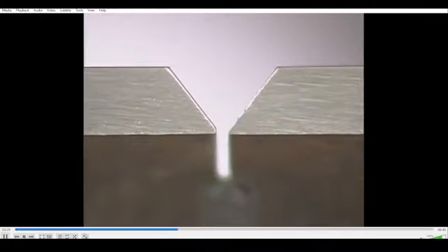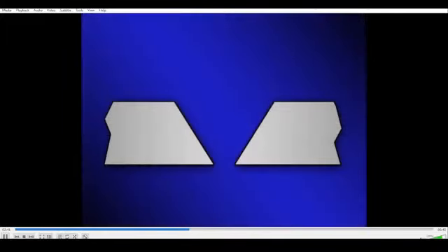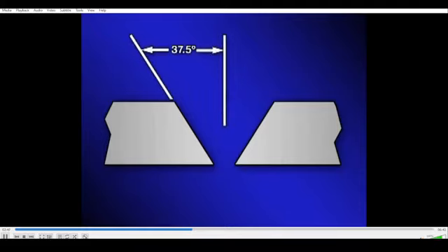As the wall thicknesses increase above 1/8 inch, both edges of the joint are beveled. A single V-groove weld is produced in these joints. The addition of the bevels provides better accessibility to the root of the joint. The groove angle is normally 75 degrees, which is made by preparing each edge with a 37½ degree bevel. The root opening is normally 3/32 to 1/8 inch in width.